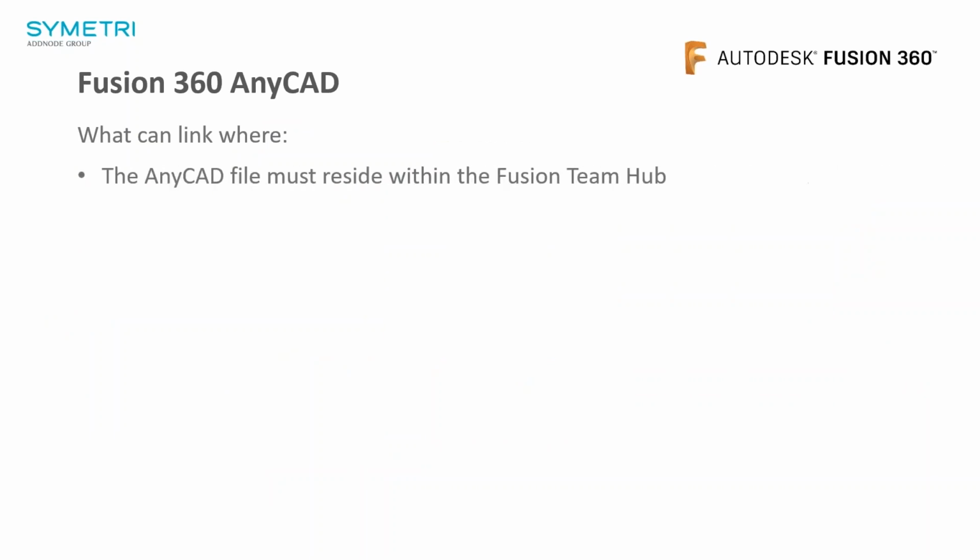Okay. So Fusion 360 to Fusion 360 AnyCAD, what can you link and where can you link it? The AnyCAD file, which could be a STEP file or SolidWorks file, must reside within your Fusion Team Hub.